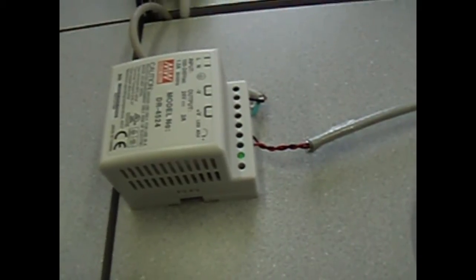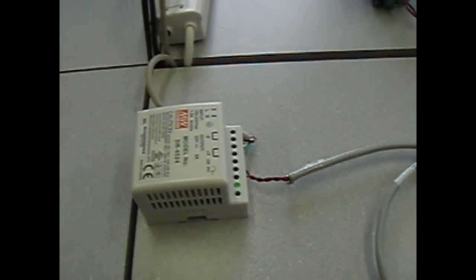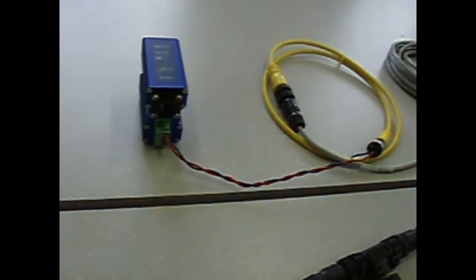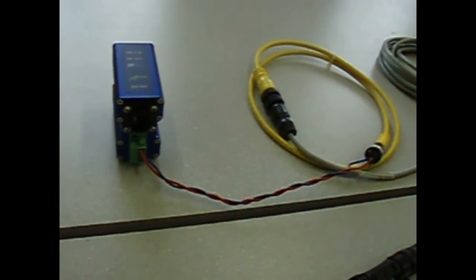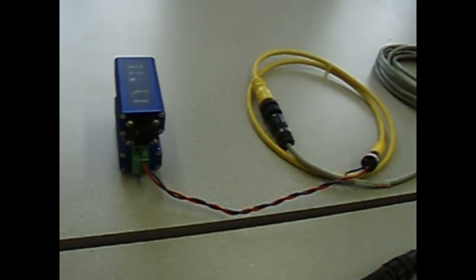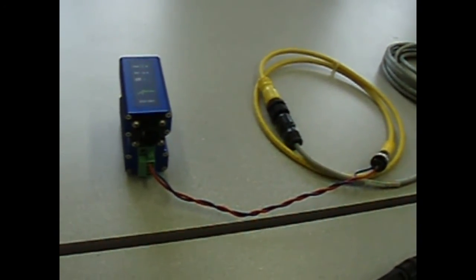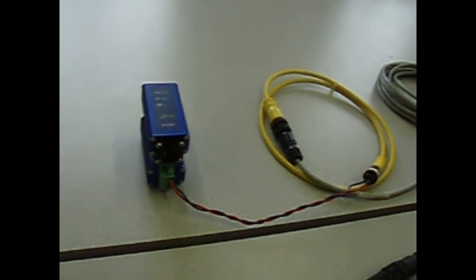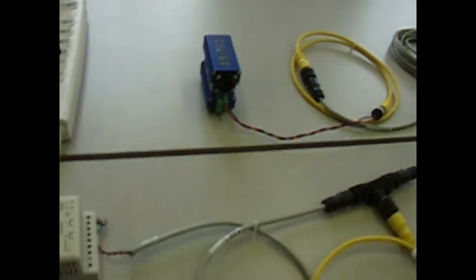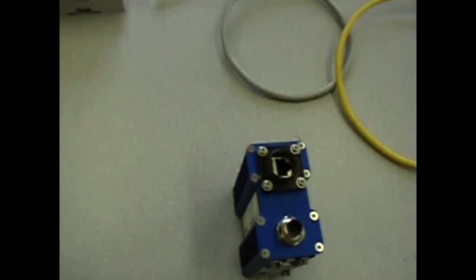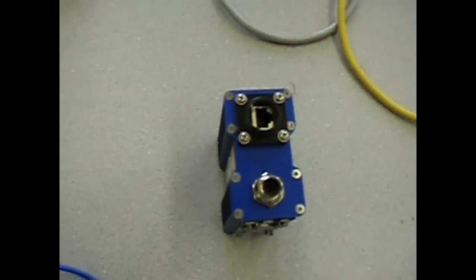And for proof that we are using only one pair, we have one of the drops of the net bridge using a terminal strip version to show only two wires that provide power as well as signal to that particular unit. The other units will have a standard DeviceNet connection, so they'll be very simple to connect to an existing DeviceNet application.